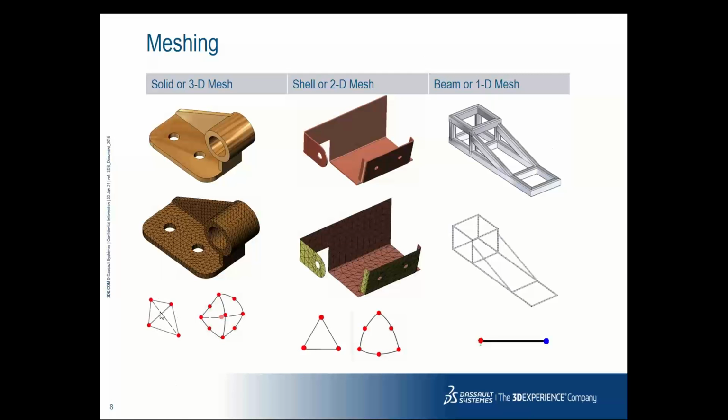So this is how they are represented. Here you can see it is a tetrahedral element that I have shown. There are two types of tetra elements or shell elements we can use. One, there's a draft quality. Whenever the software develops the linear differential equation, I hope you must have learned about differential equations, when the power of the differential equation is 1, at that time, it will create this kind of tetrahedral element. When I increase the power of the differential equation, it may be 2, 3, 4, or any polynomial power, there are certain nodes that are introduced in between the two nodes.